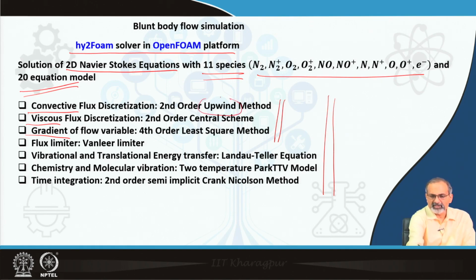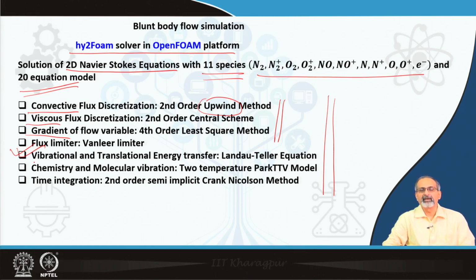With strong advection effects, you have to use upwind schemes for the stability of the solver, and then with strong shocks and discontinuities, flux limiting has to be done in order to keep the solution stable and also clip off the oscillations which occur across strong changes.